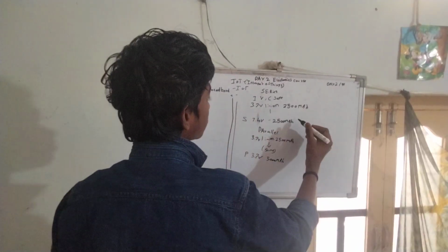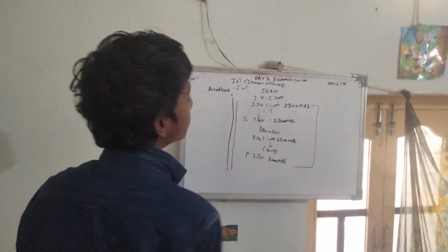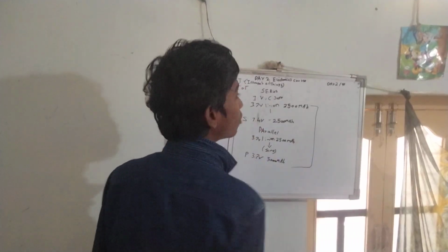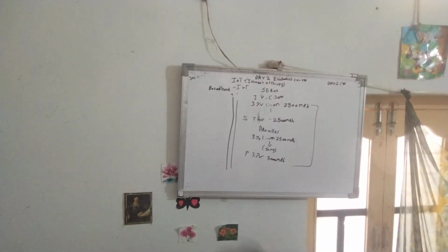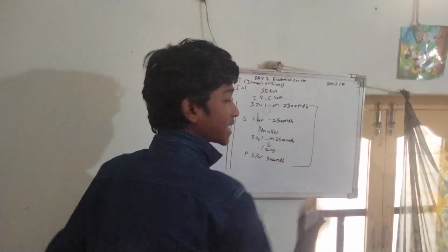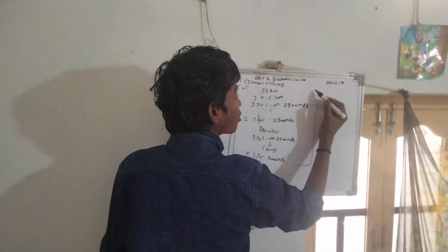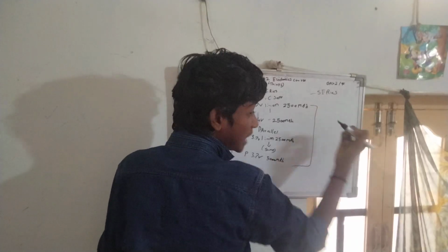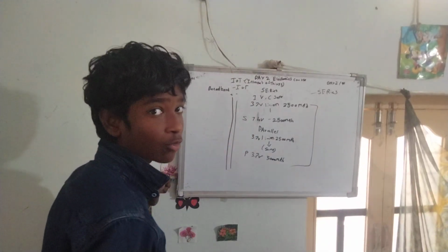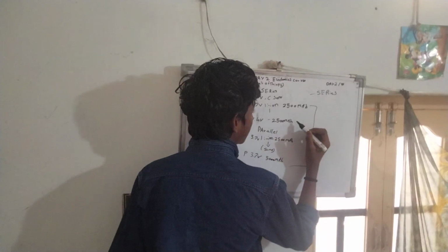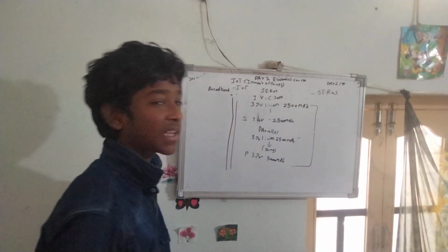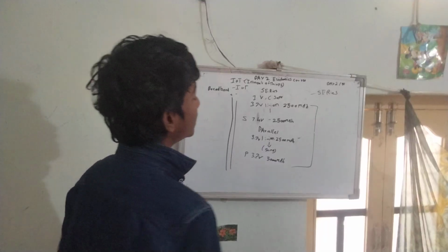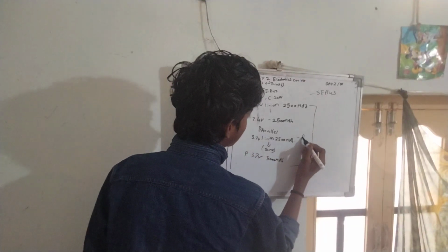So both of these are equally used in many sectors. For example, if I need more voltage, but the capacity being the same is okay for me, I can go with series connection. If I need to power more devices or I need more voltage. Now, if I want more time, the capacity, more runtime on the battery, I can go with a parallel connection.